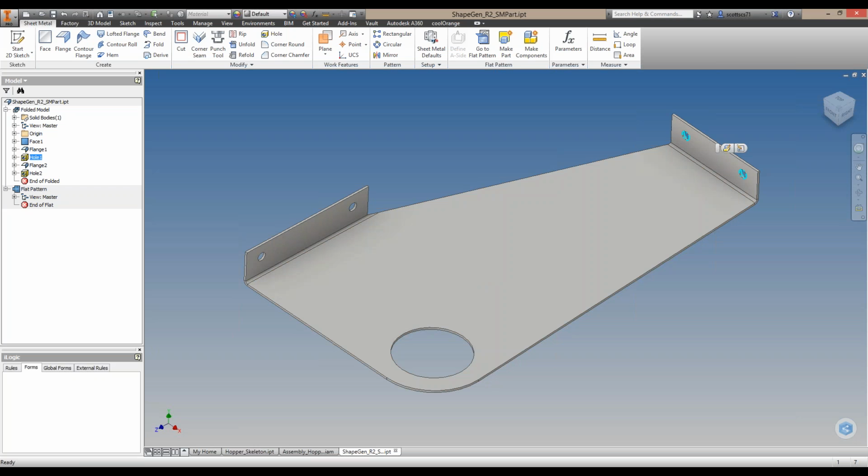So let me get this set. The way the shape generator works is that it utilizes the stress analysis environment by moving it up front in the design process, and it balances out metrics such as factor of safety and, in this case, mass. I want to remove some of this material. I want to make this lighter, to lighten up this overall assembly that I'm creating, to optimize the design and essentially leave you with the minimal amount of material you need to meet your